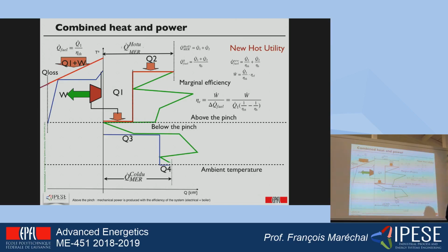When I'm looking at the composite curve, it's even better if I'm looking at what is happening below the pinch. Because below the pinch, I know that I have too much heat. So if I was asking you, give me the highest temperature at which you can take the heat out. The reason for this is that if I have heat at high temperature, I can use it to evaporate a fluid, which is perhaps not steam. It can be another refrigerant.